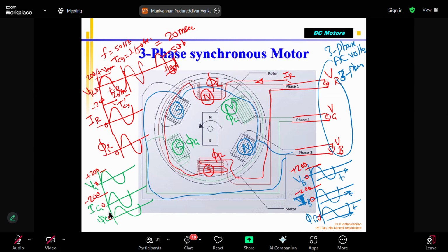Okay. Now that you understand the three-phase motor has three sets of coils, the projections are called poles. I told you previously that the stator body is laminated magnetic material, on which there is a projection that is called a pole. Correct? There are 6 poles in this motor, or 3 pole pairs. Right, in the three-phase motor.